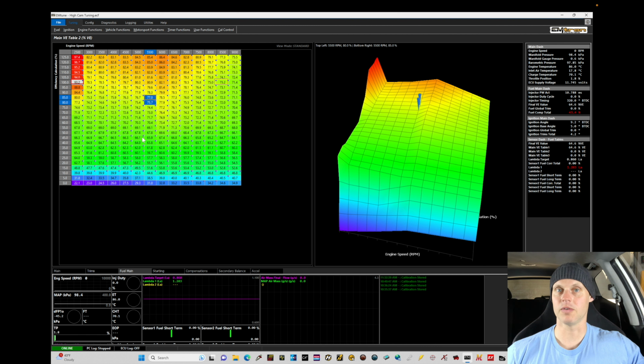And what we need to do from here is go into our cam switched output status, where we're controlling our VTEC, and set that up so we're locking ourselves into VTEC and being able to go in and command it at a very specific condition. We want to lock our VTEC in really low so we can get into the high cam and map everything out. Then we can overlay our low cam and high cam pools and figure out where the two torque curves intersect or cross. That's going to be where our VTEC activation's at.